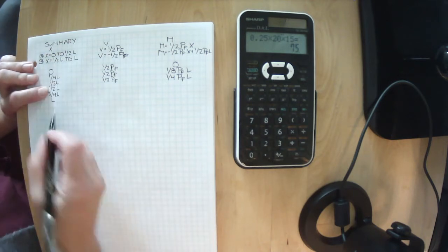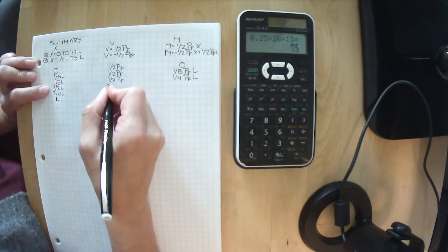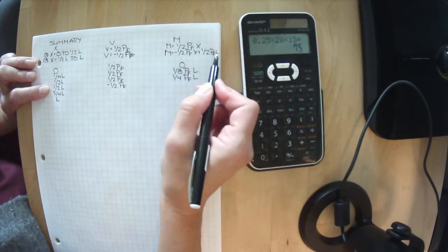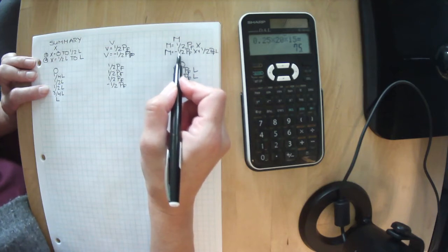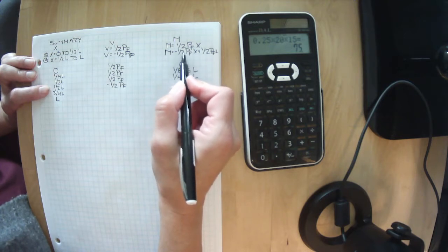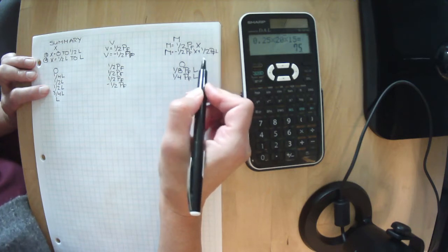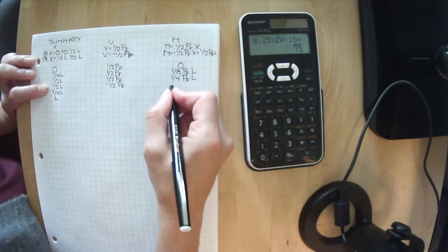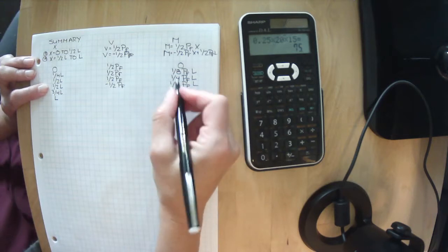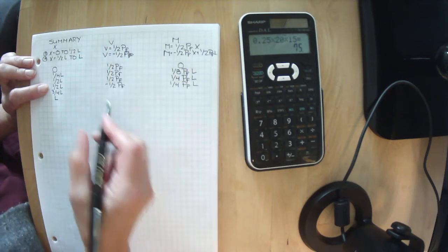Let's look at the other half of the beam now. So we have 1/2 L being plugged in here. Doesn't matter. It's minus 1/2 PF. All right, let's plug 1/2 L into this. So minus 1/2 PF times x, or minus 1/4 PFL plus 1/2 PFL. Minus 1/4 plus 1/2 equals 1/4 PFL. So we get the same value at the midpoint no matter what side of the beam we're at.